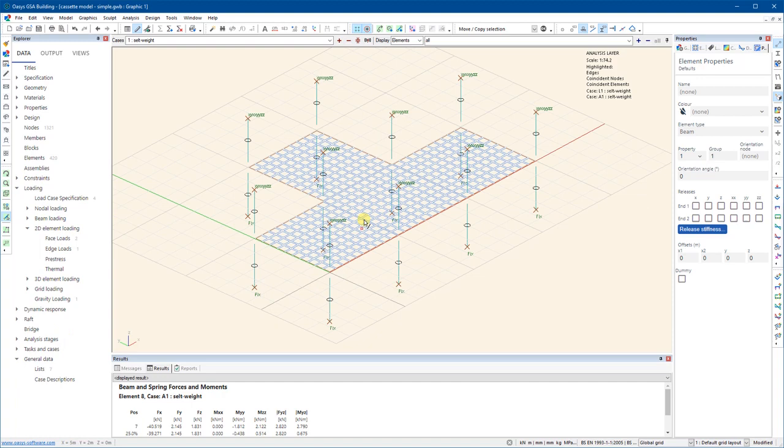You don't need to save lists to type anything in here. So again, if you look in the GSA help, it tells you how to define various types of elements. So 2D elements are area elements. So if you go PA, so property of area elements, and I type PA1, all of these elements have the same property.